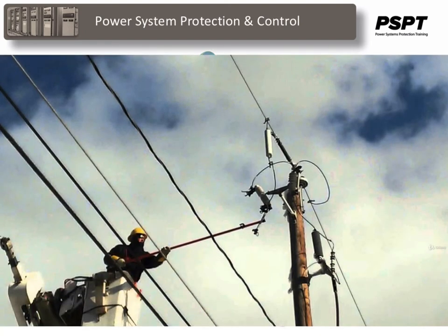One type of indication that the fuse has blown is the dropout type fuse holder. When the fuse blows, a catch is released on the upper end of the jaw, allowing the upper end to fall due to gravity. The spent fuse holder pivots on a hinge at the bottom end of the fuse holder and remains suspended from it, a clear indication that the fuse is blown and the circuit is open, and it's quite visible from the road.